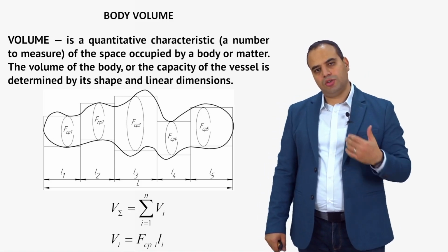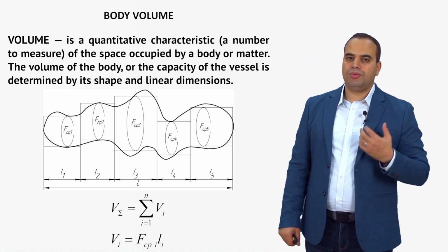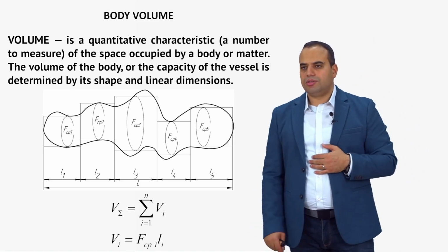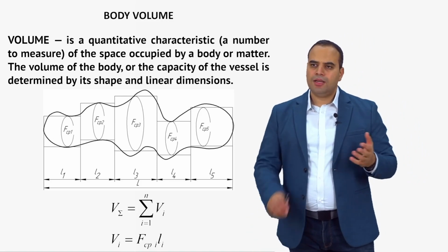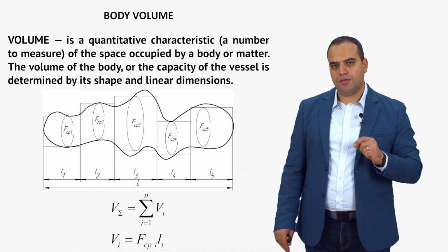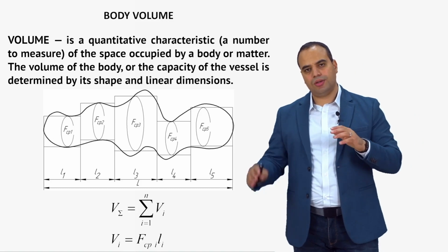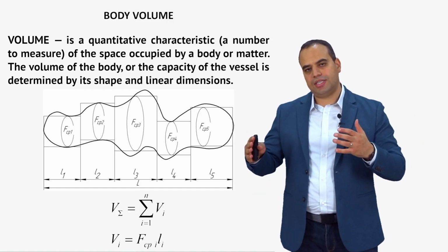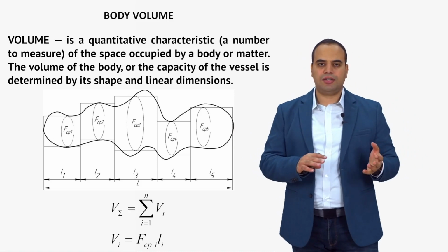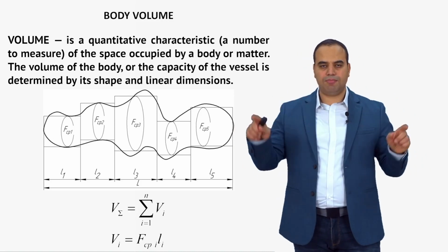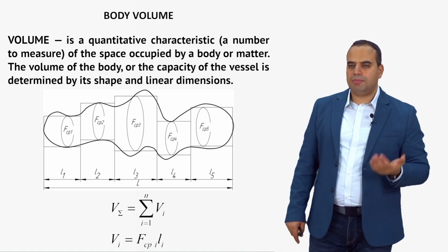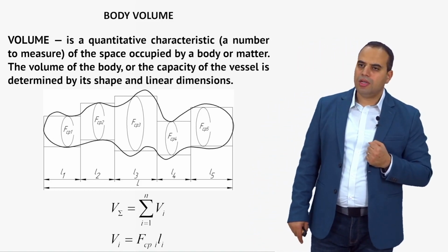So we have to calculate the volume pretty much all the time when we integrate systems inside of the airframe, because as you know, the outer geometry of the aircraft, which is called the theoretical contour, is a fixed boundary. So we cannot fix anything outside of it, because it has to do with the aerodynamic characteristics of the aircraft. So the outer geometry creates a boundary, and only inside of that boundary can we integrate our systems, payload, fuel, and so on.